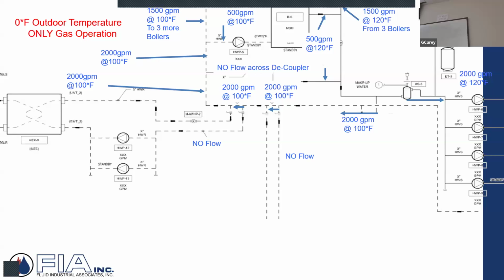What's the cost of a therm of natural gas versus a kW of electricity? So that's when they start to balance and saying, hey, I know you think gas is bad, but right now gas is really good when it's 0 out. When it's 30, okay, we'll shut him off and we can use the electric, and the COP's high enough on my heat pumps that it might make sense. If I got a COP of 2.5 or 3.0, okay, for 1 kW, I'm getting 3 kW worth. Okay, that makes sense. I can justify that.